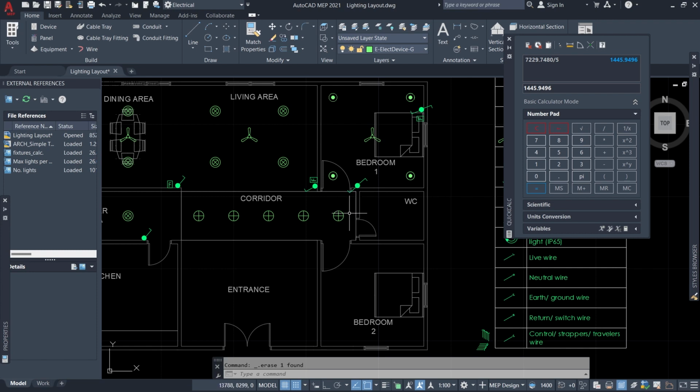That's the concept. So what that brings to light is that we need, again, one gang or a two gang, but we need a two-way switch over here. Okay, so I'm going to put a one gang one-way switch here.